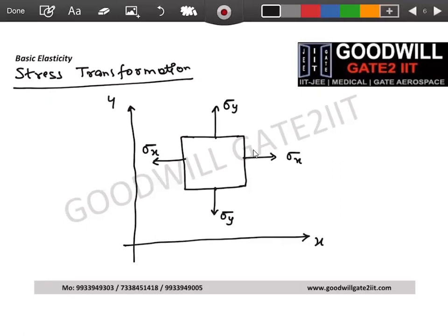All right. And we have seen shear stresses are complementary in nature, meaning on 2 mutually perpendicular planes, they are equal and opposite. So if this is shear stress, let's say tau xy or sigma xy, you can write anything. On a plane perpendicular to it, it will be exactly same tau xy and in the opposite direction. Similarly, if I'll see here, something like this and something like this. So I've not written tau xy everywhere because we know this is one shear stress only which is present everywhere. So this is also tau xy, this is also tau xy, and this below one is also tau xy. This is a typical 2D stress element.